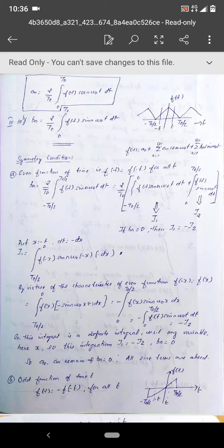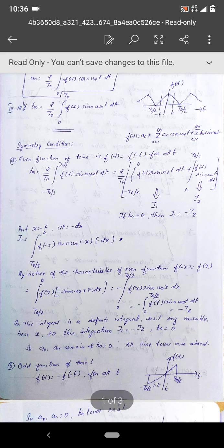So welcome back. In the last lecture we have seen how we represent any arbitrary periodic waveform as a summation of a DC term, or an average value, and many sinusoidal waveforms, starting from the fundamental frequency right up to the nth harmonic. So we can write any arbitrary periodic waveform as an infinite summation from zero frequency to multiples of the fundamental frequency, or as a sum of so many sinusoids. That is what we have seen.